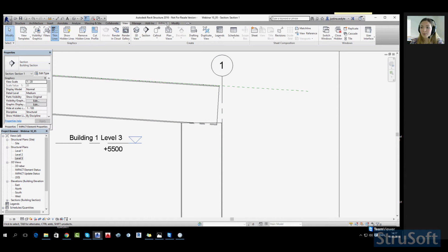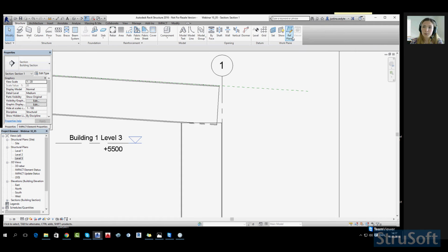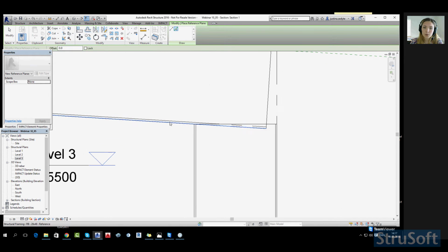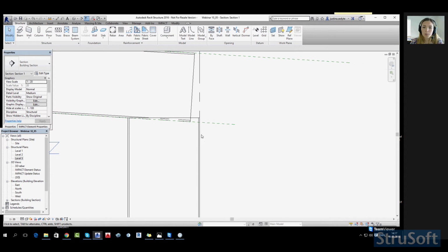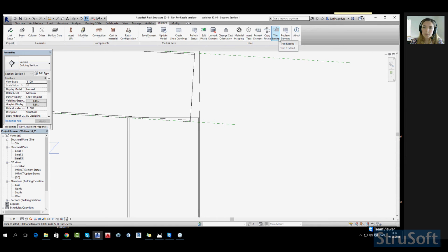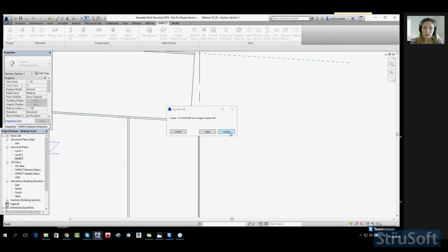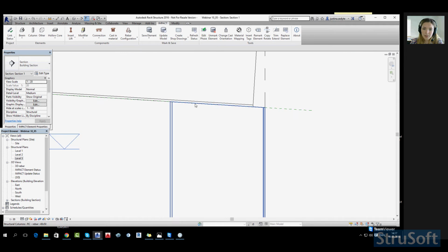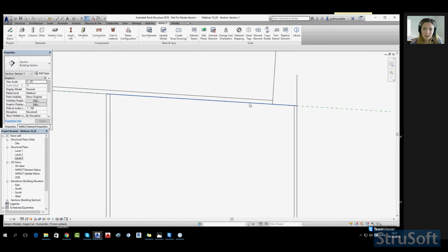What I want to do now is basically I want to trim a bit this column. To do so, I have 2 options. I can do that in a 3D, or I can use a trim extend function with the reference line. If I want to do the second option, I have to go for the structure and draw a reference plane. I will just pick already existing line. And I want my column be like this with the same reference line.